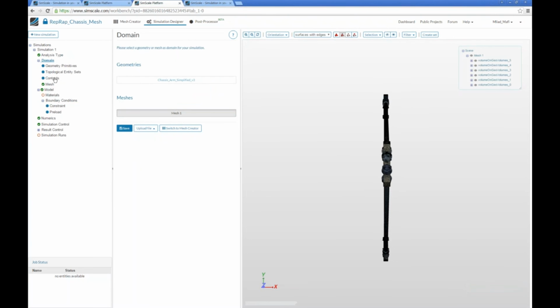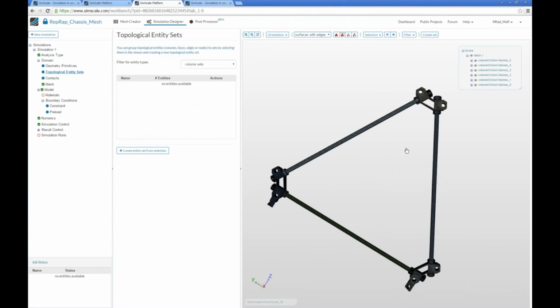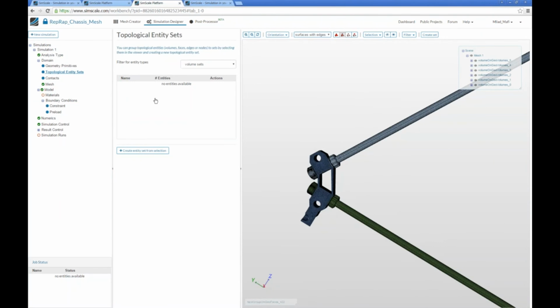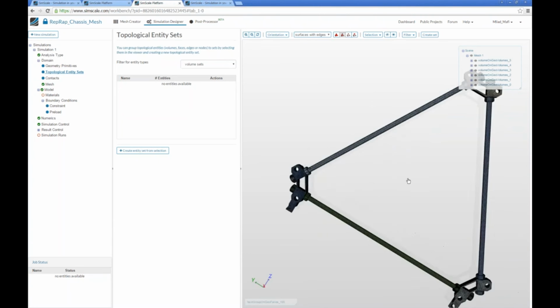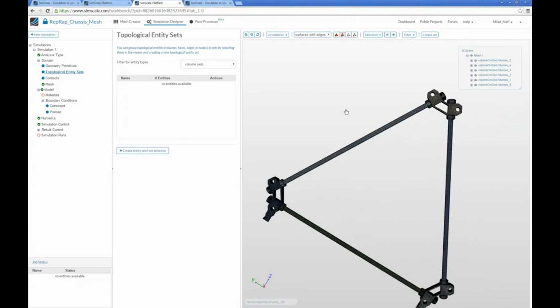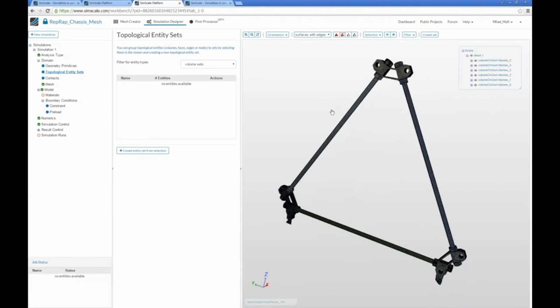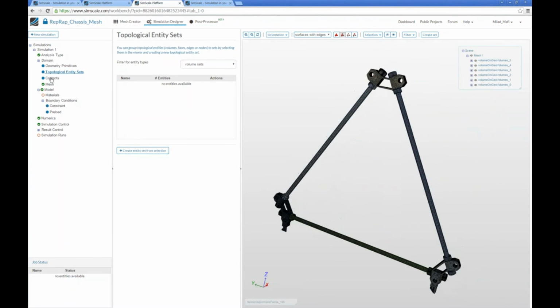The next thing is not red, but it's also very important. It's called contacts. It's new, this part of the tree. And as we discussed, we need contacts. And there are two opportunities. You could first create these face groups, entity sets, and then create the contacts out of them. This is maybe a little bit more comfortable if you want to do a lot of changes later on, but since we want to make it faster and very easy, we'll do it directly.